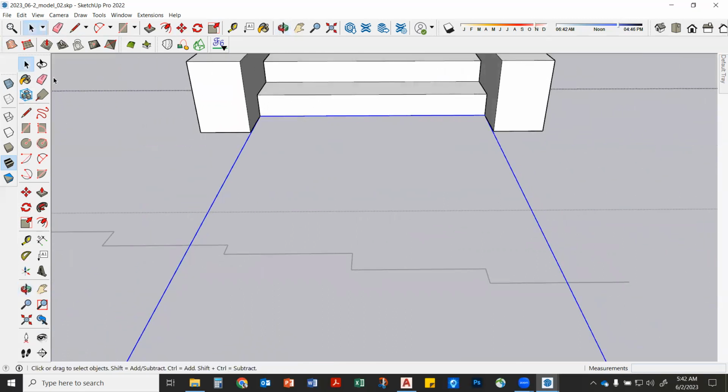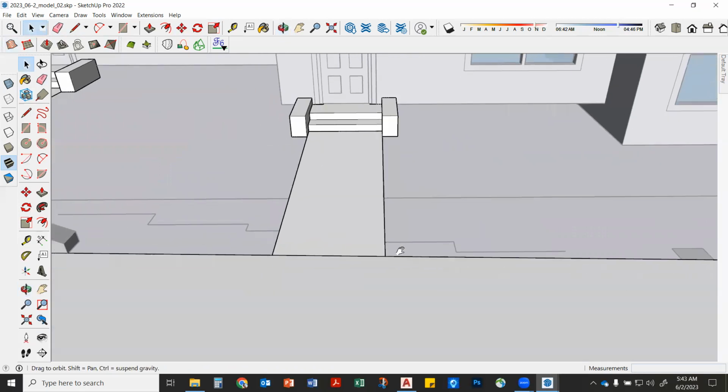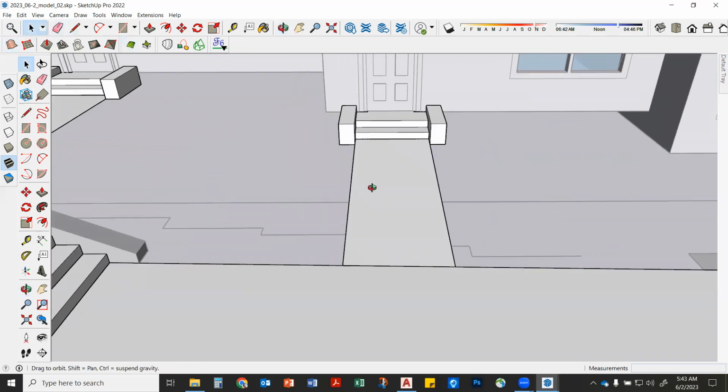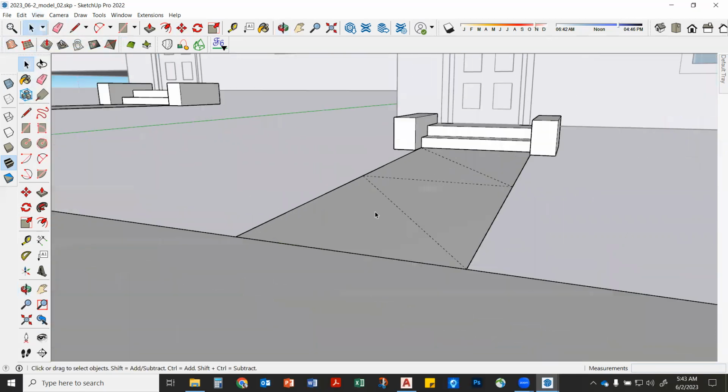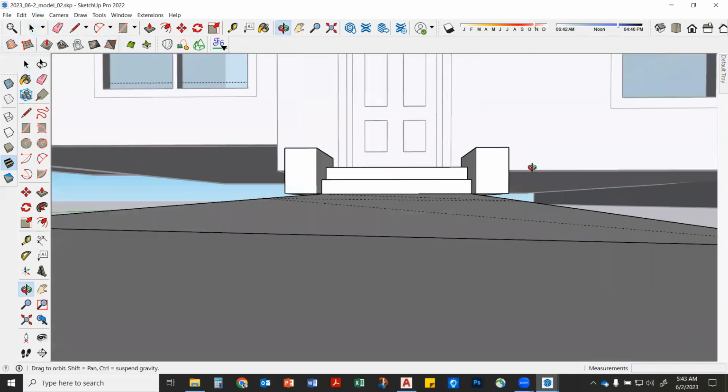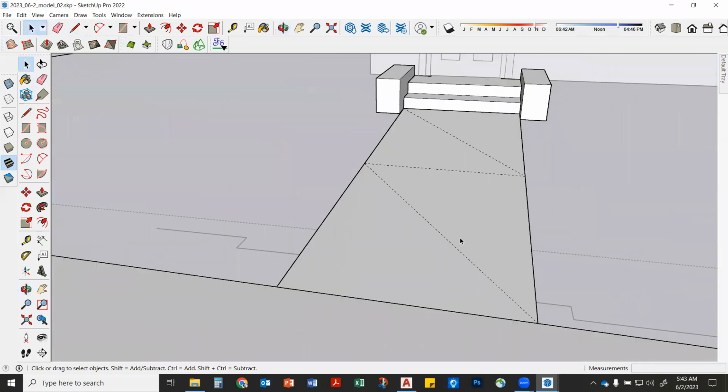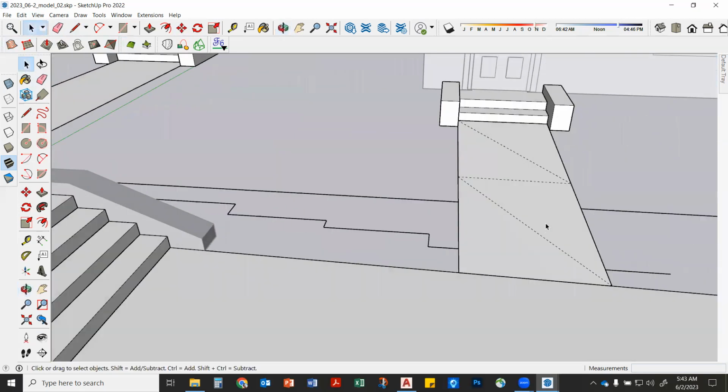So once they're all selected, I hit from tool or from contours. And then it gives me this nice thing. Now you can't even tell it's sloping really, but that's why I often keep on my hidden geometry. So you can say, oh yeah, you can see there's a bit of a slope to these. Okay. How was that? It's good, right? Good.